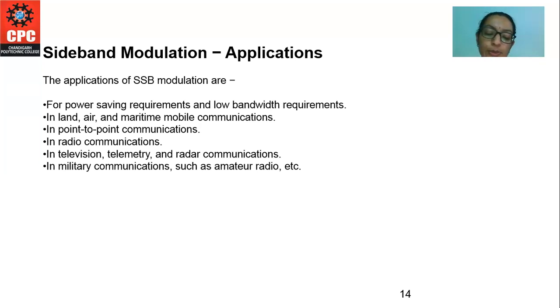First, we know that the SSB transmitter and receiver require excellent frequency stability, and a small frequency shift in the system will deteriorate the quality of the transmitted signal. Therefore, it is not possible to transmit good quality music effectively using the SSB system.